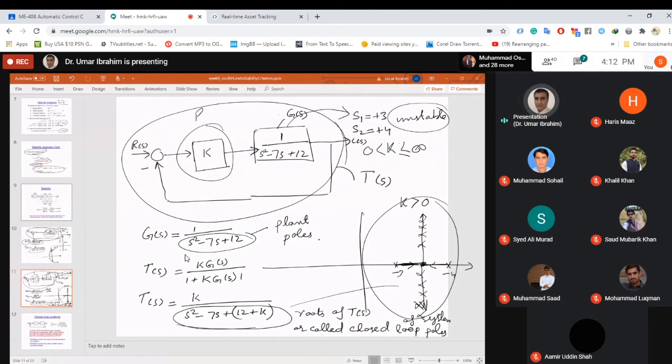Looking at this path, can you see this path ever coming into the left-hand plane? No, sir. So what is the conclusion? I'm going to ask you a question, you will have to answer it. Would any value of K from 0 to infinity make the whole closed loop transfer function system stable? No, sir. Looking at the root locus, your answer is no, which is the correct answer.